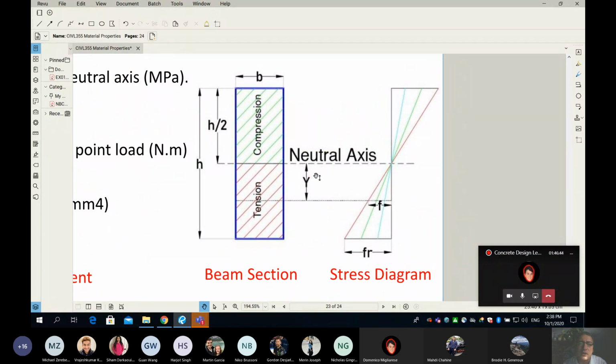And simply when I start from 0, and then I keep increasing my F a little bit, what happens to the moment? The moment will increase. So there will be a bending moment that's trying to bend this beam. And remember, the load is very little. And remember, my beam has no reinforcement, zero reinforcement. It's just plain concrete. Okay?